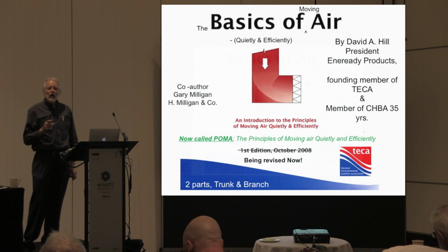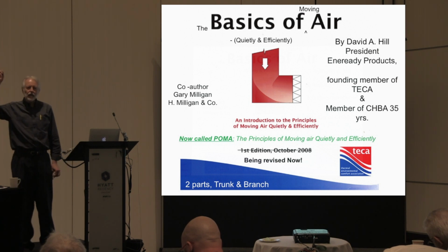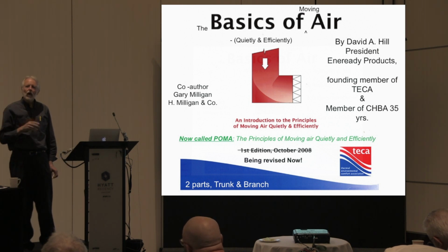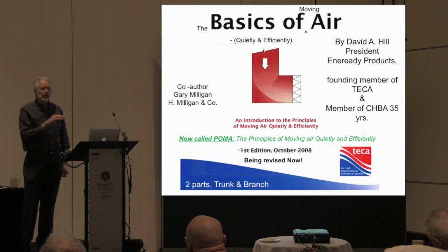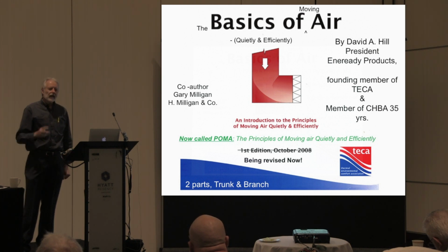Number 2, if Mrs. Smith is cold in her bedroom in the winter or hot in the bedroom in the summer, what's the problem? It's probably because the branch is not big enough. And that's a whole different issue with design and installation of sheet metal, is getting the air to the bedroom. And lastly, I'm going to talk about duct leakage because it's a big, huge issue.